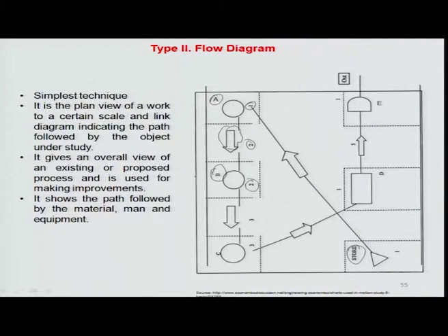So operation B is being performed in station 2, and similarly the material flows again between 2 and 3, where operation C is being done on the particular workpiece. So you are representing this in terms of transportation and operations, and then it goes to an inspection station 1, where inspection activity D is carried out, followed by transportation to another area where the output would go from.